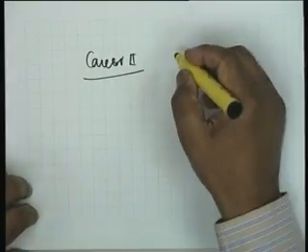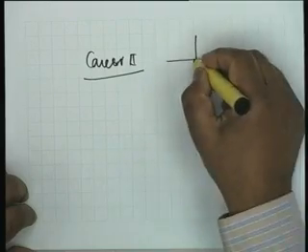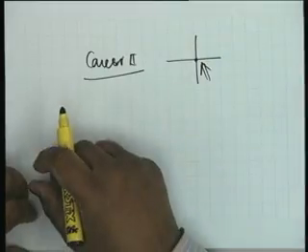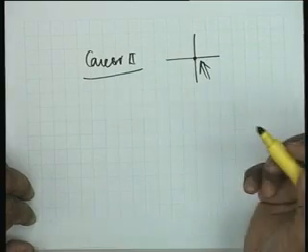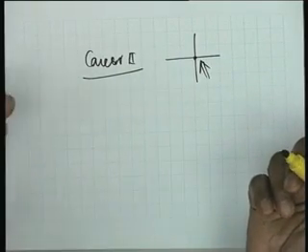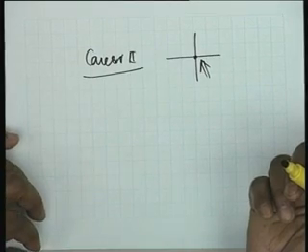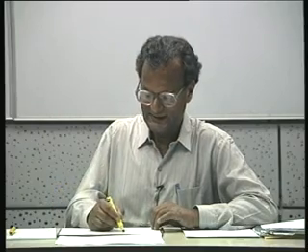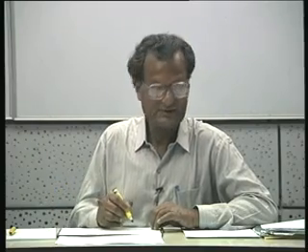Cauer 2 focuses the attention on the point at the origin, s equal to 0. Okay. This is the point which you look at. Now, at s equal to 0, what is it that we can remove from an RC immittance function? Obviously, it is the constant from ZRC or YRC? YRC. Therefore, Cauer 2 must start from YRC. There is no other way.